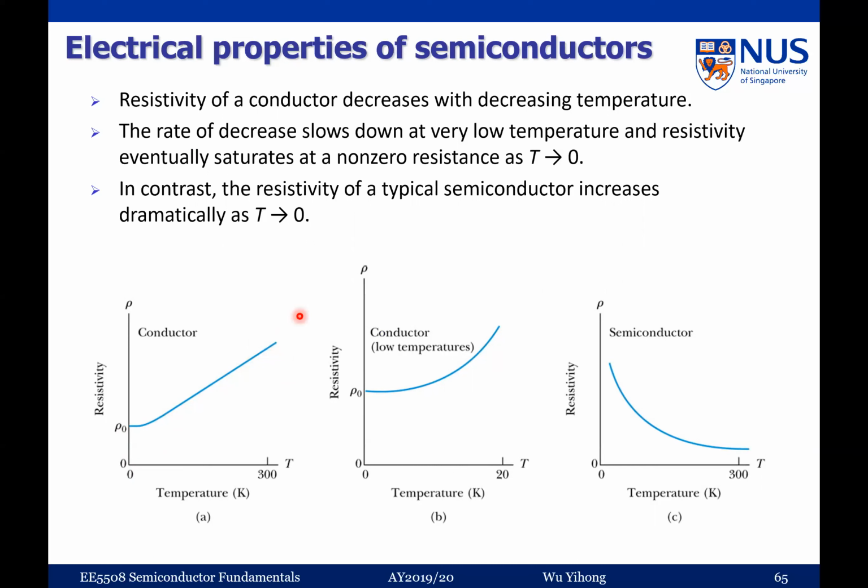And many of the very good superconductors at low temperature have quite high resistivity at high temperature. So why is this the case? Because their conduction mechanisms are actually totally different, right? Of course, you have so many different types of superconductors. We won't go into details, but if you are doing materials research and you find a material whose resistivity is quite high at room temperature, you should not exclude it as a potential superconductor. You only know this when you reduce the temperature and see how the resistivity changes.